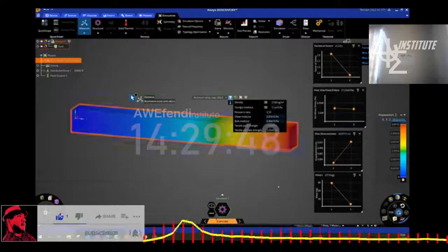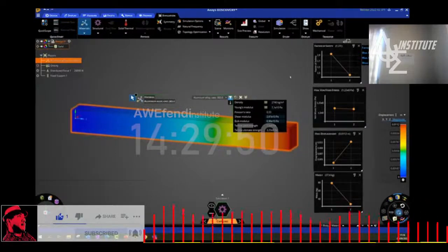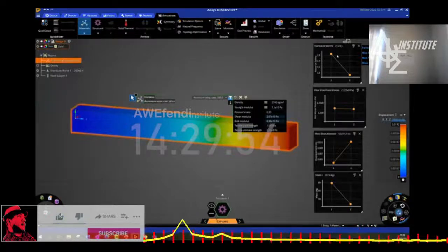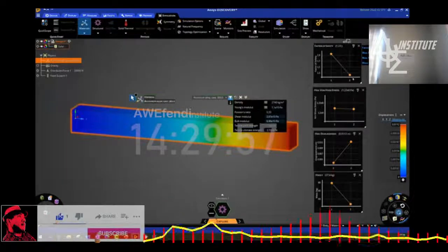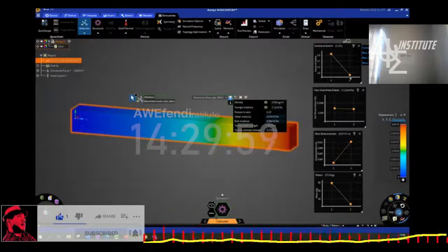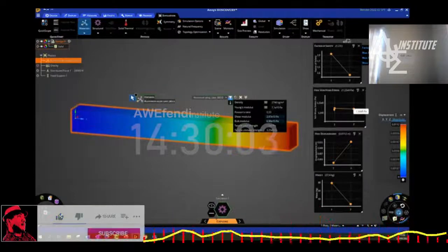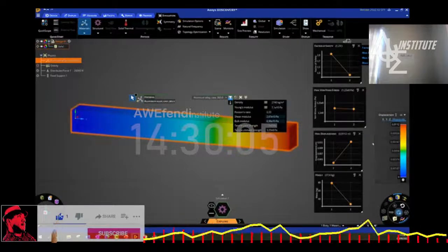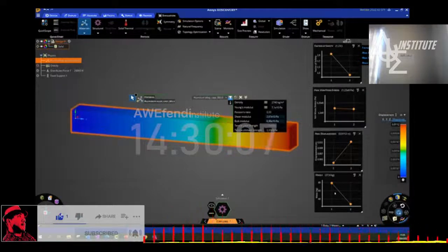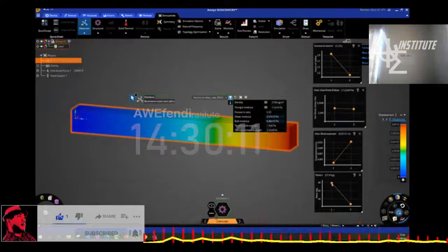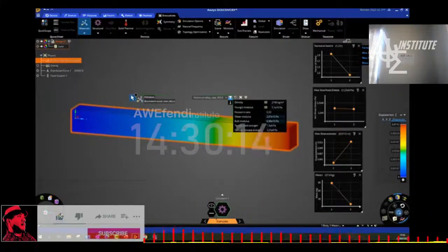There was instantaneous feedback, and now we have results. And you can even validate this model this way. For example, you can see the factor of safety has decreased, which is expected when you switch from steel to an aluminum alloy. The stress remains the same. Maximum displacement has increased. And we know that aluminum has a lower density than that of steel, so obviously the mass has decreased.